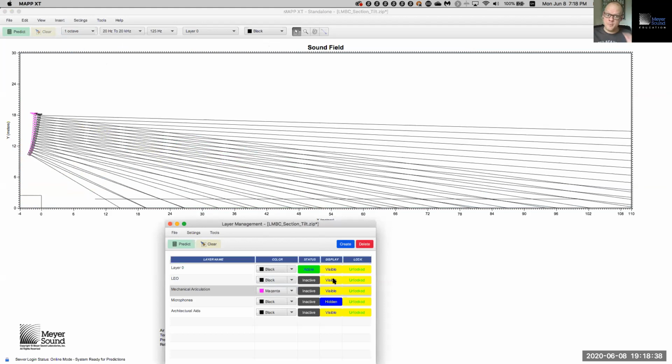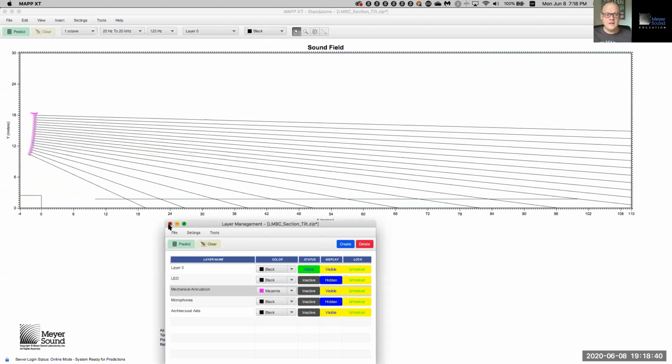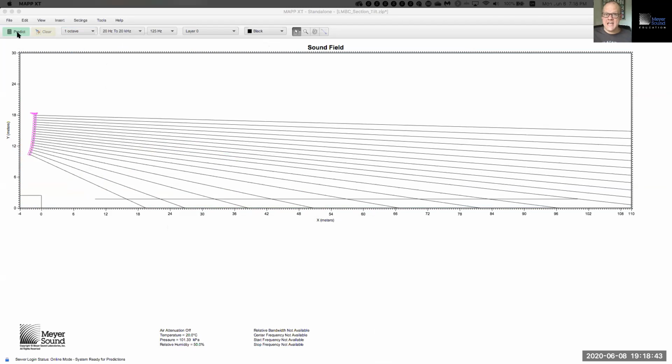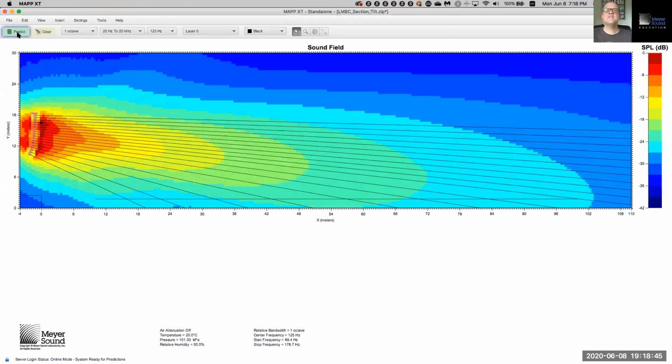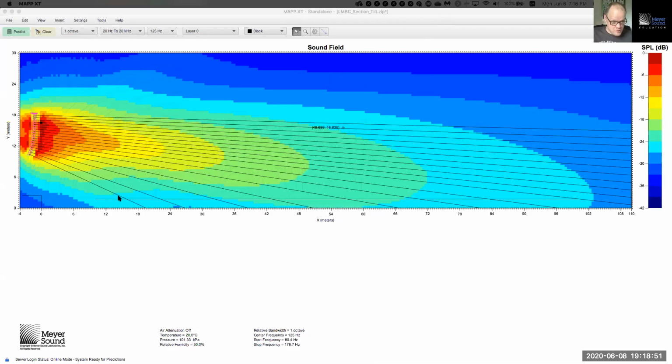I just want you to appreciate that if we were to deploy the array like this, the same concentrated amount of energy now goes where it needs to go, which is to those distant seats, introducing a much more gradual drop in level over distance. The trade-off is that about 60% of your waveguides are pointing in the wrong direction. So again, we cannot do this mechanically.